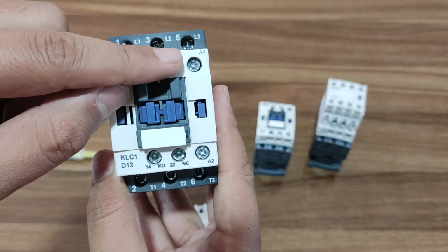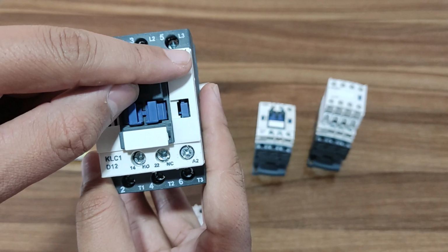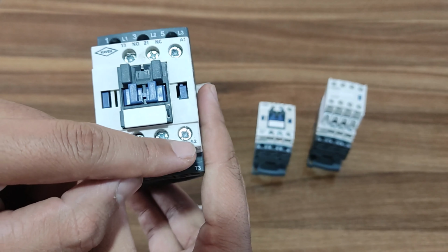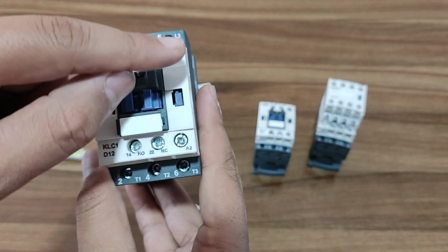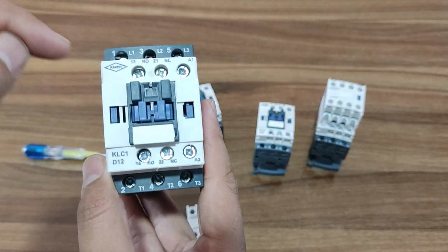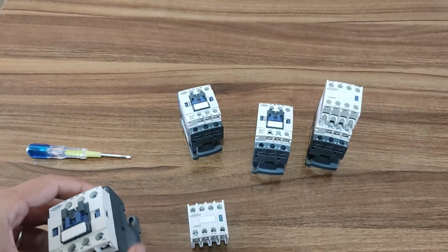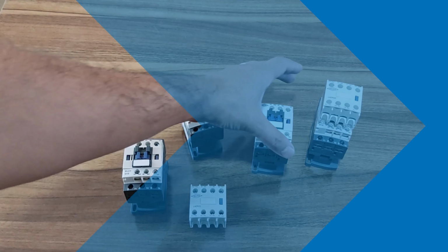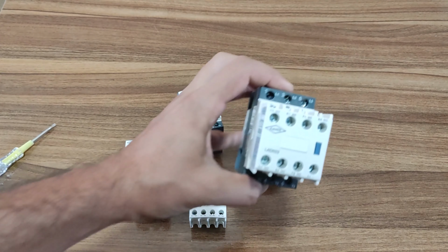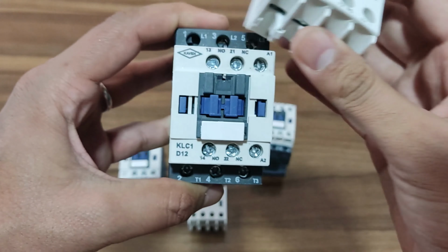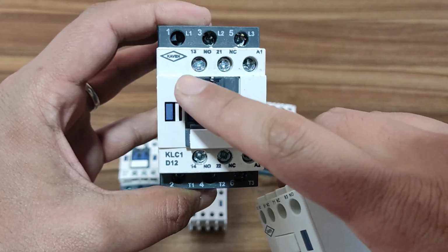On the contactors, 2 or 3 other terminals may be considered to connect the two ends of the contactor coil to the circuit. These terminals may be marked with the letters A1, A2 or 1B and 2B in the IEC standard. In addition to the main contacts that are used in the power circuit, contactors usually have one or more auxiliary contacts that are used in the control circuits.